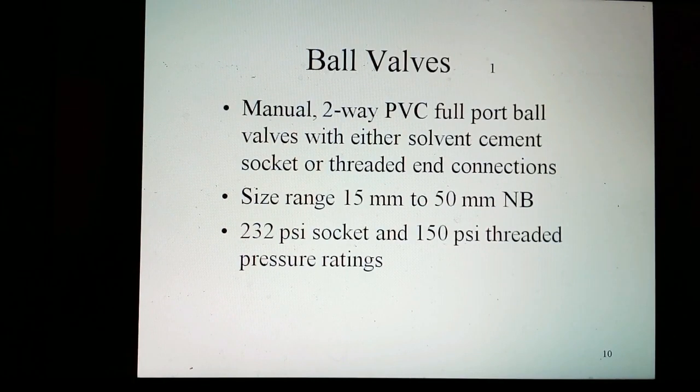Ball valves are manual, two-way PVC full-port ball valves with either solvent cement socket or threaded end connections. Size range half-inch to 2-inch with 232 psi socket and 150 psi threaded pressure ratings.